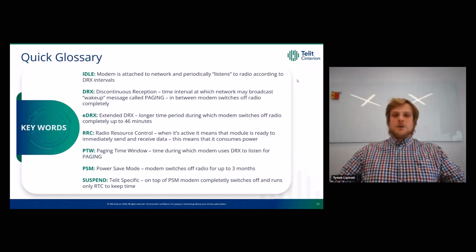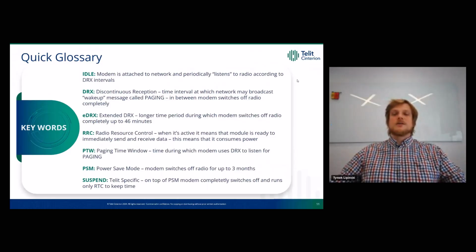PSM, Power Save Mode. Wonderful development from the 3GPP specification, where the modem switches off the radio completely for up to 3 months, and the network retains the registration and the notion of presence of the modem in the network. Ultimately, we have Suspend. This one is pretty quirky because it's a Telit specific abbreviation. On top of the PSM, where the radio is switched off, the modem nearly completely switches off and only runs the RTC, meaning real-time clock, to keep up the time and to know when to wake up when the power save mode timer expires.